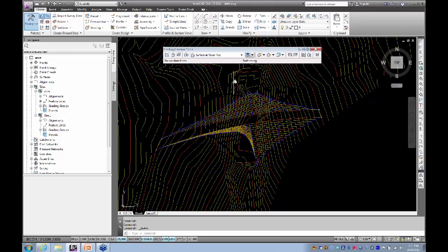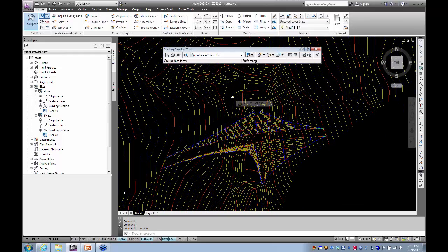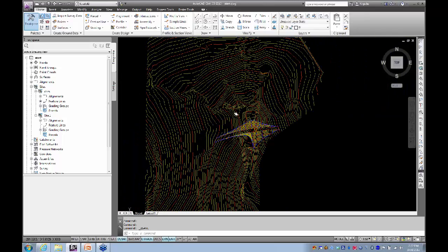So we probably want to make a combined surface out of these two, and then we can play with water levels up the back behind the dam. And then we'll look at cutting a bit of a spillway in here, perhaps. So what I'm going to do, and if you've forgotten this, it's a good thing to know, I want to combine or paste together the dam surface and my existing ground surface. That's what I'd like to do.